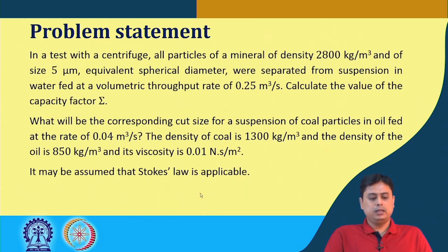for several types of centrifuge, such expressions can be derived and can be used for certain calculations. For example, say in a test with a centrifuge, all particles of mineral density 2800 kg per meter cube, of size 5 micron, that is the equivalent sphere diameter, were separated from a suspension in water at a volumetric throughput rate of 0.25 meter cube per second. So, you have to calculate the capacity factor.